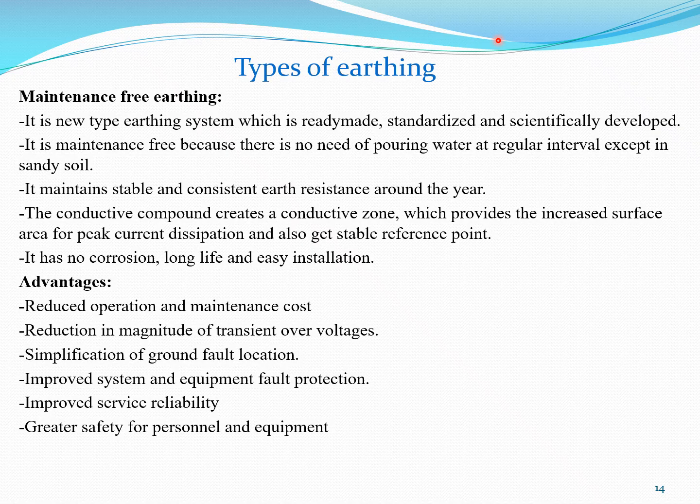In maintenance free earthing, chemical earthing electrodes, usually made up of galvanized iron, copper, or copper bonded steel, are used. The electrodes are surrounded by the earth enhancement compound, that is EEC, such as bentonite, clay, graphite, or mineral salt, which retain the moisture and maintain the consistent resistance.